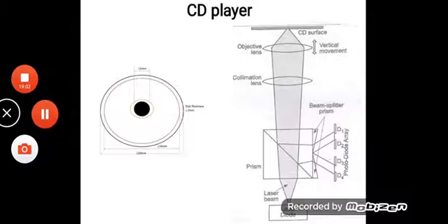So this way we can identify whether the laser beam has hit a 0 or a 1 on the CD surface, and with the help of the photodiode assembly, the photodiode array, we can get the values recorded on the compact disc in the form of pits and flats. Those are nothing but the values of ones and zeros. So in short, while reading, we get the stored data in digital form, as ones and zeros.